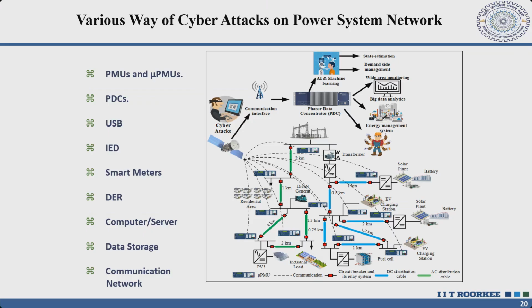So usually nowadays in our country, smart meters are installed for HT consumers, high tension consumers. These consumers are those who are utilizing three-phase power at 415 volts or higher level. And they are billed by the company, the Discom, using a two-part tariff.